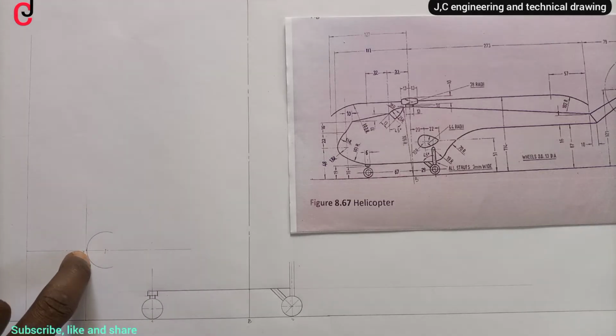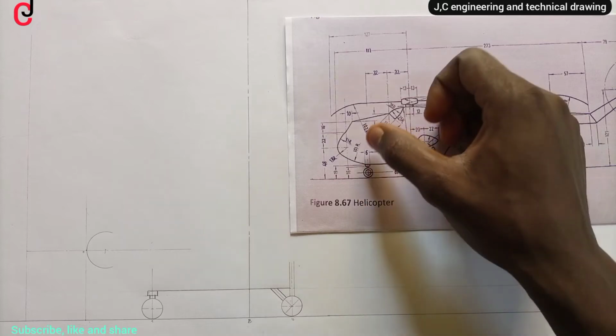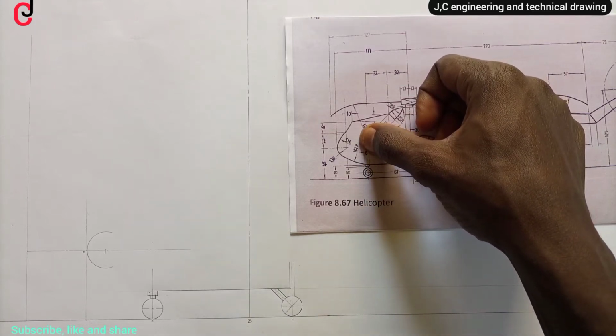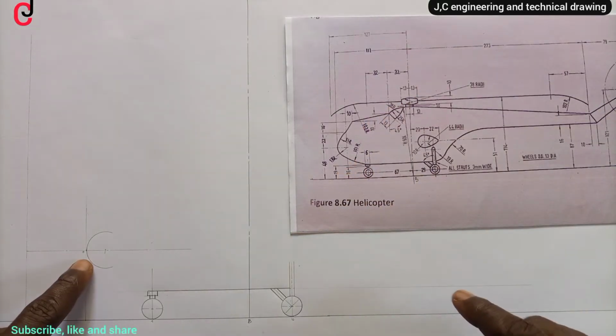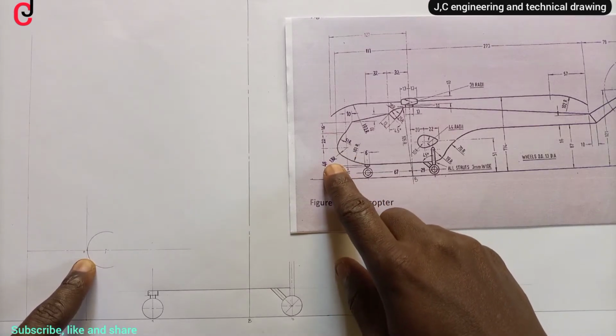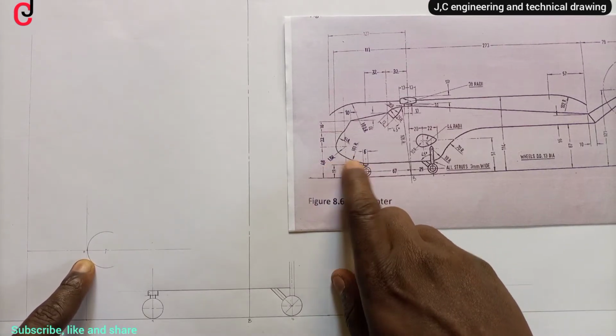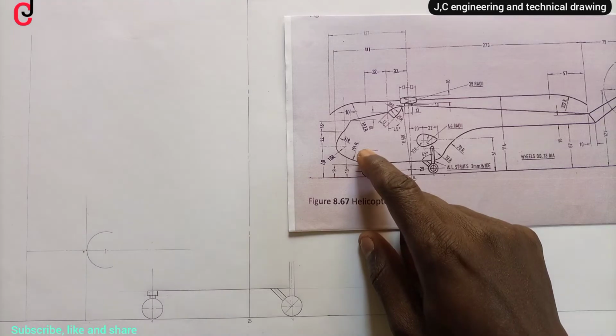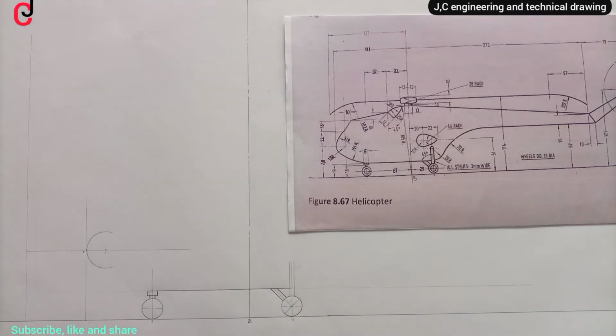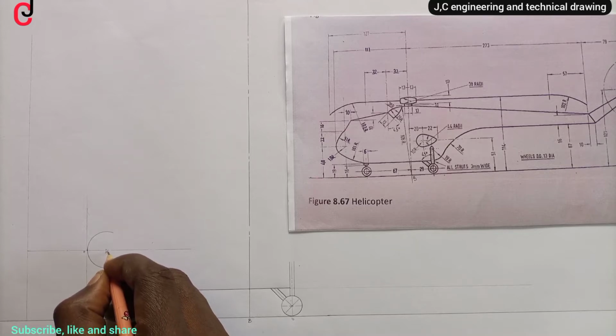So we succeeded in drawing our semicircle. The next thing we're going to do is join this 101 millimeter radius. There's an arc of 101 millimeter radius touching a circle of 13 millimeter radius internally. When circles touch each other internally, you subtract. So subtract 101 minus 13, which will give us 88 millimeter. We'll call this point here point O2.